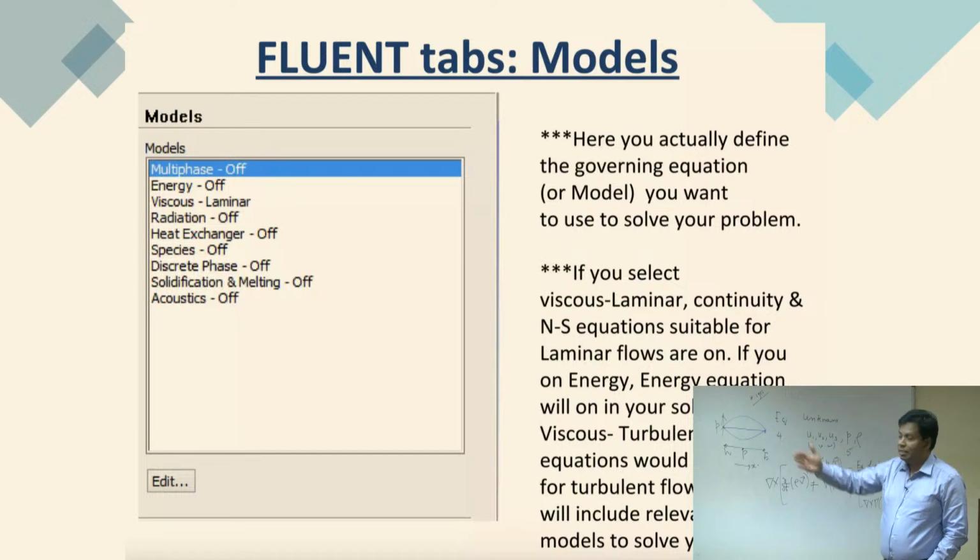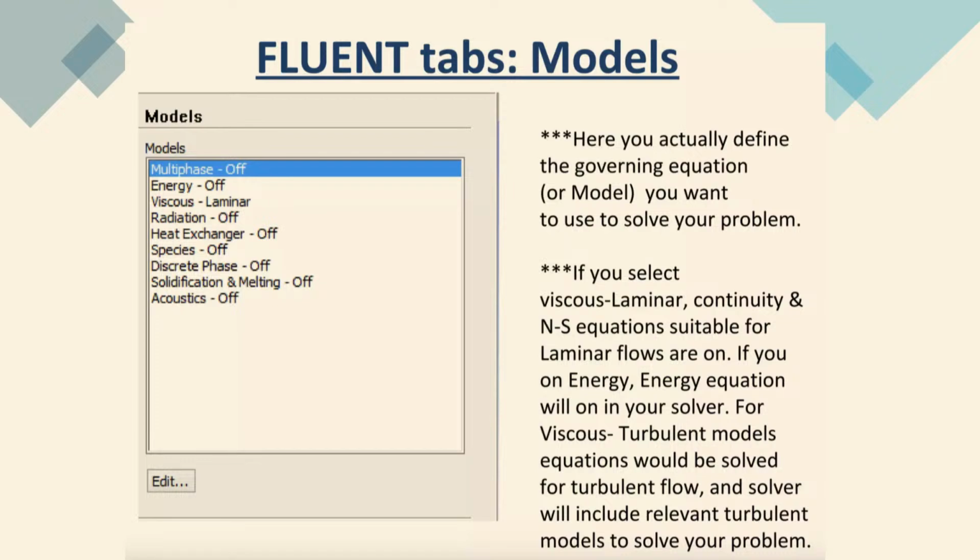Are you using the heat exchanger? You have to tick it on. Or are you solving any species, any concentration related problem like a diffusion problem? You have to tick this on. Are you solving any discrete phase, or doing any solidification or melting? My group is working on phase change material, which means a solid phase becoming liquid when the temperature rises. So, this time we need to turn on solidification and melting. Mostly it is called a thermodynamics problem. And acoustics, are you doing it or not? Those are very important, and you have to check, as all the equations are different.